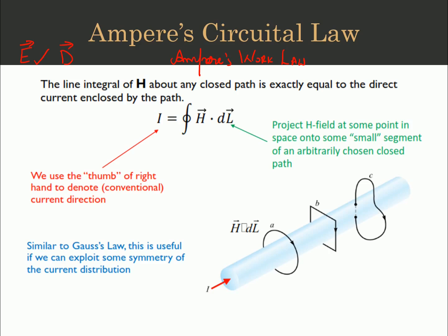closed line integral. So we can say that the Biot-Savart law resembles Coulomb's law, not exactly, but to some extent. And the Ampere's law that we are going to study now is similar to Gauss's law, where Gauss's law was defined as a closed surface integral of electric flux density in order to find the charge. So Ampere's law is on similar lines.